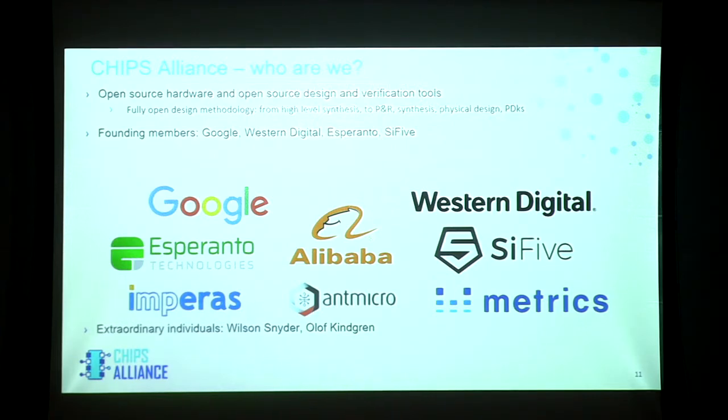And eventually, we want to generate a fully open design methodology from RTL simulators through design verification flow to place and route and synthesis. Eventually, in some far future, we want to create partnerships with some foundries, get open PDKs, and sort of create an open flow. Right now, that's the dream. The focus is on the more immediate projects, which are RISC-V cores, some other interesting pieces of IP, like open source neural network inference IPs, open source RTL simulator tools, open source design verification tools, etc.